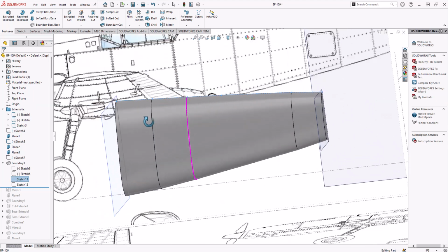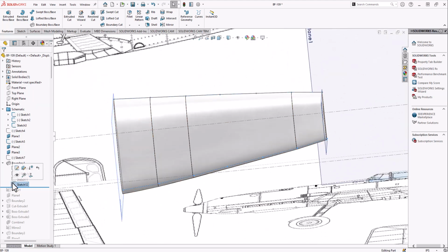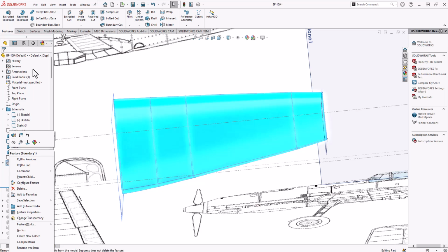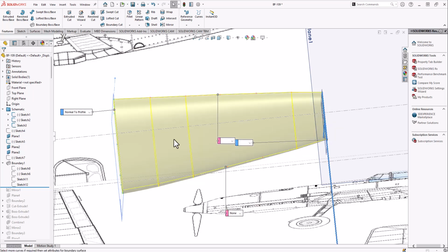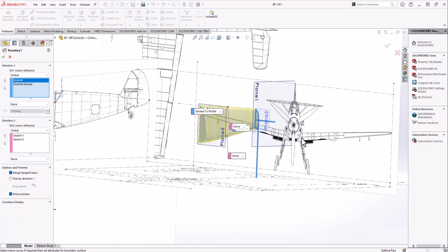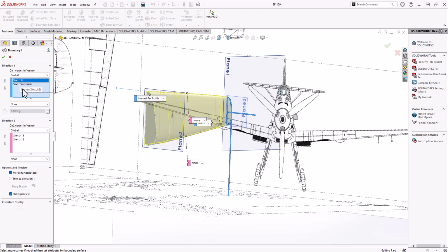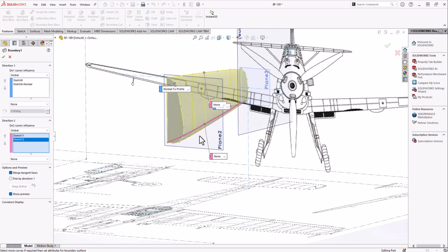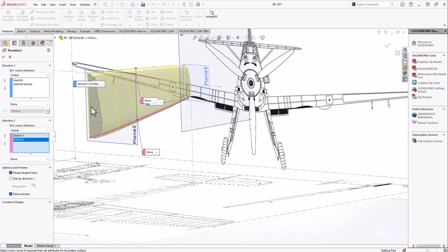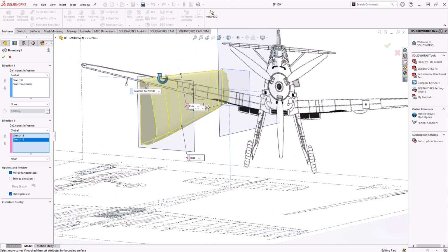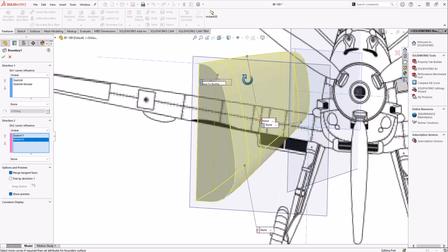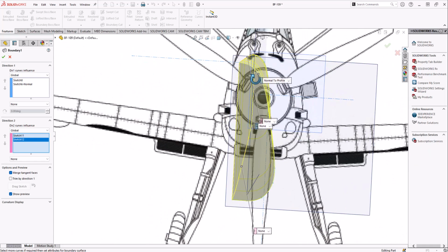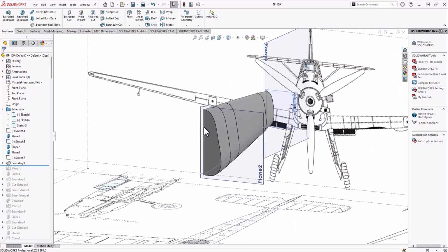And then the other component, there's two more sketches here. So there's the top guide curve and the bottom guide curve. And what that looks like within the boundary sweep, or I guess it's a boundary boss base, if I open that and edit the feature, you can see that I have my two sketches here, and then I have the guide curves down here. What that lets me do is map between these two front and back faces, and then it will ensure that it goes along these guide curves. So it creates some pretty nice geometry for what I'm doing, like so.